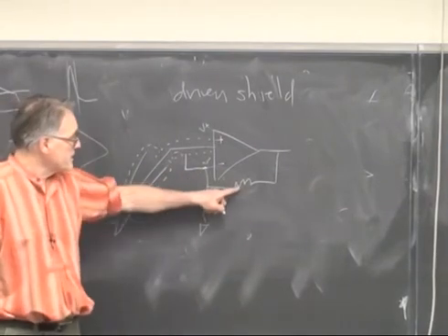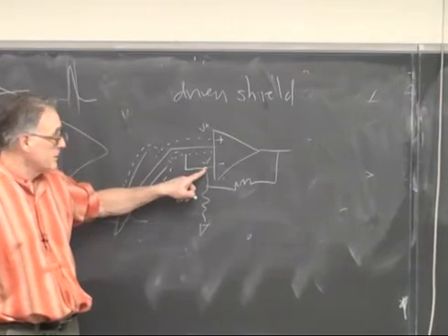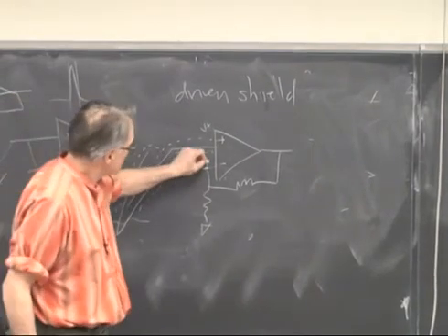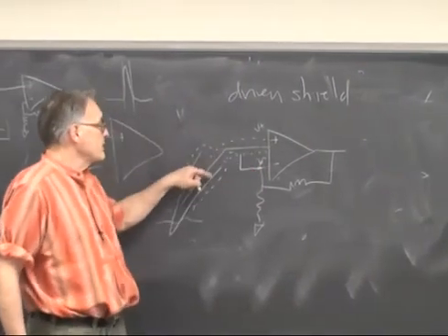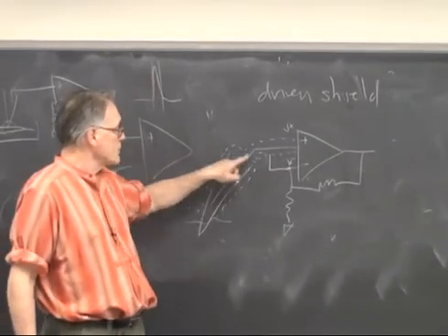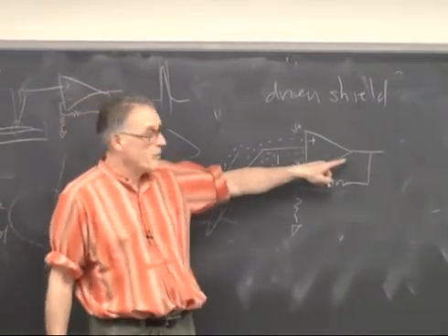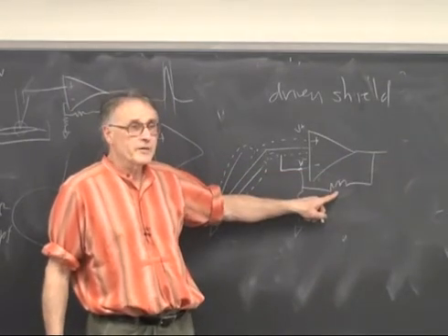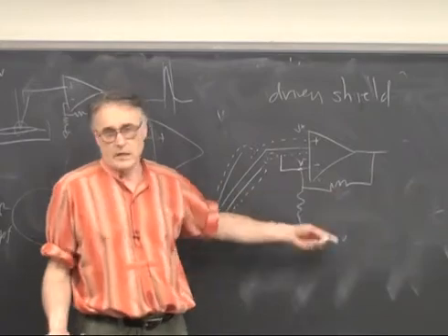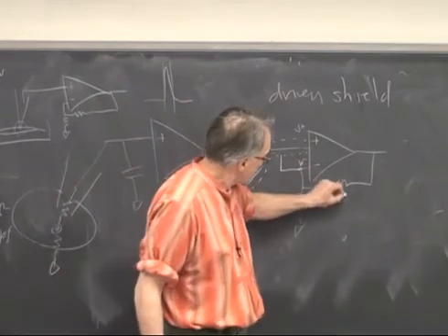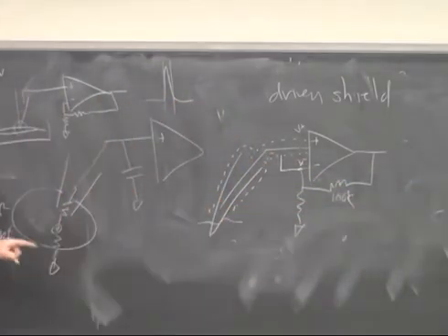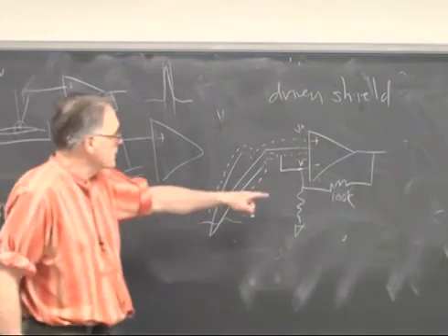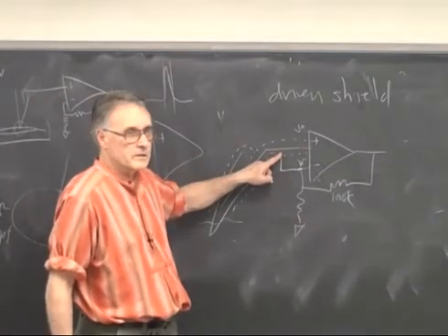Okay, there is a resistance in series with this point, with V minus, and so it does take some amount of time to charge this capacitance through the output voltage. But if you use any kind of reasonable feedback resistor, let's say 100 k ohms, then the time constant is a factor of 1,000 lower or so, and so the charging is essentially instantaneous.